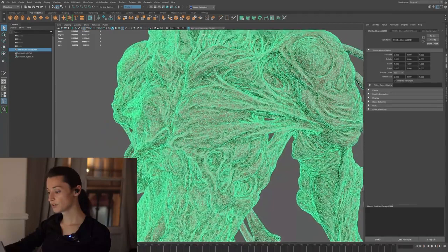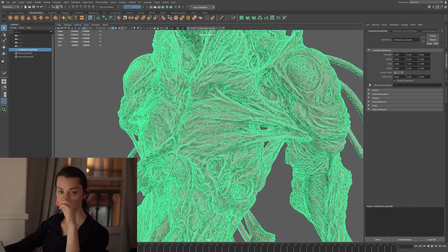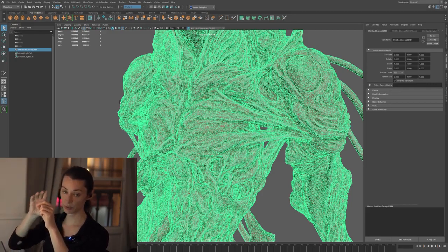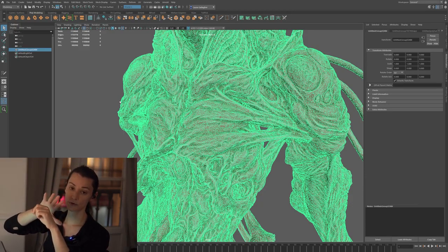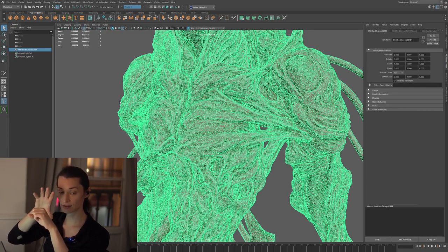But regardless, before we can actually draw any polygons over the surface of this model, the first thing that we need to do, of course, is to convert this object to a live object. And that is within Maya the way that we specify that a particular object is one that we want to use Quad Draw on top of. So all the vertices that will be moving around the scene, they will all automatically snap to this live object.